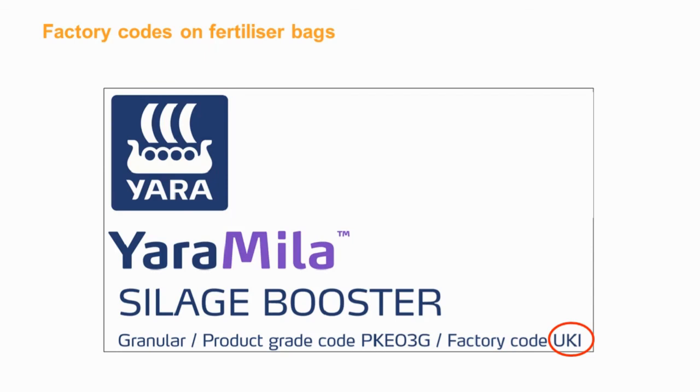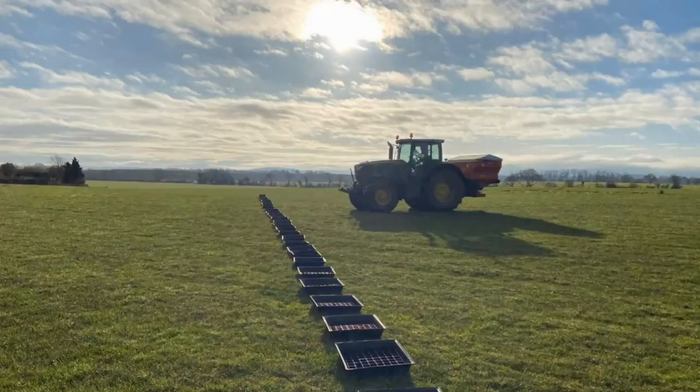So these spreader manufacturer settings, while they are useful, are only ever a guide, because they're often only based on one spreader and one fertilizer sample in a spreader test tool in Europe, but they obviously do provide convenience to you. And although we provide good consistency from bag to bag and year to year, the only guaranteed method of matching the product you have purchased with your spreader is to do a tray test. Qualified engineers will ensure an even spread pattern at your chosen bout width, and their services are recommended.